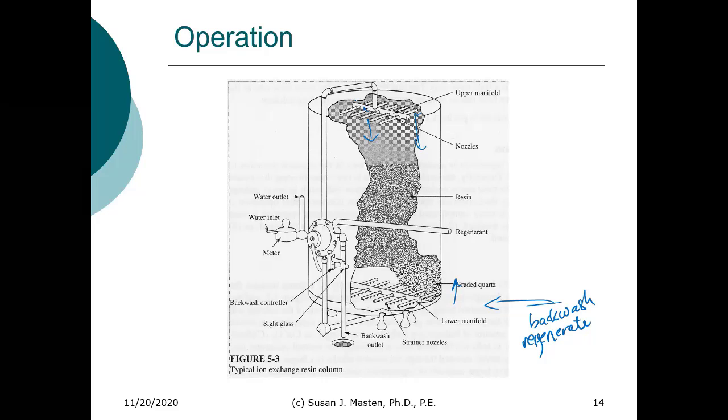The treated effluent from their wastewater treatment plant, they were discharging not into a body of water, but into a deep well. And he said that they stopped doing that because of the softening units. Anybody catch that? So what was the problem? And he said what the contamination was. He said that it was salt contamination.